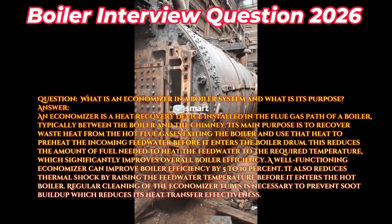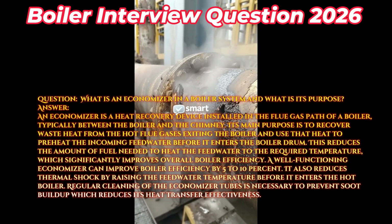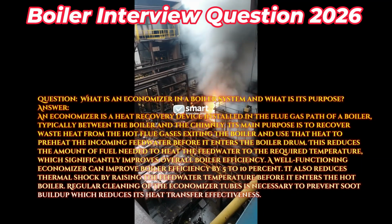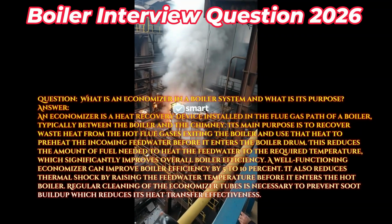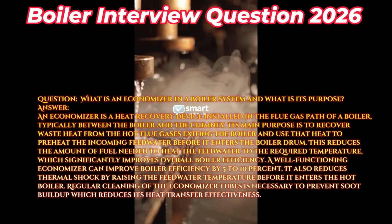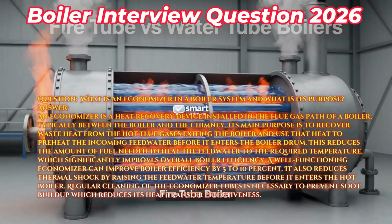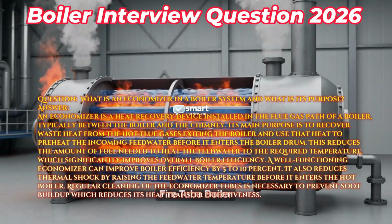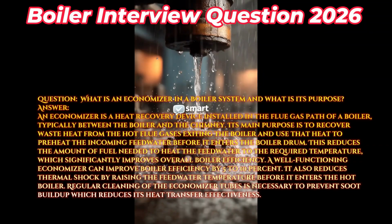This reduces the amount of fuel needed to heat the feedwater to the required temperature, which significantly improves overall boiler efficiency. A well-functioning economizer can improve boiler efficiency by 5 to 10%. It also reduces thermal shock by raising the feedwater temperature before it enters the hot boiler. Regular cleaning of the economizer tubes is necessary to prevent soot buildup, which reduces its heat transfer effectiveness.